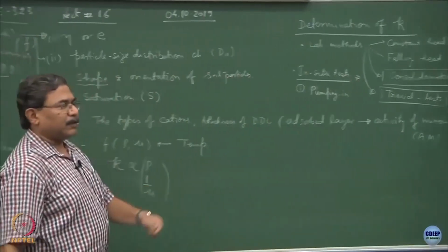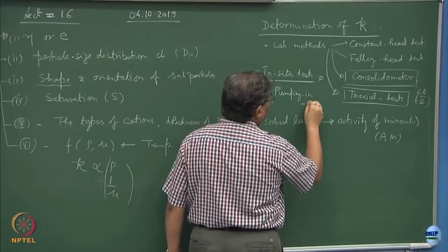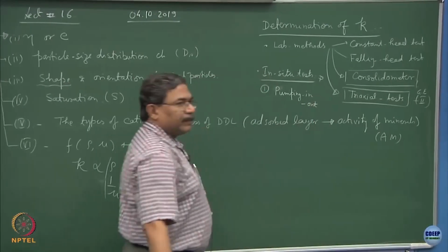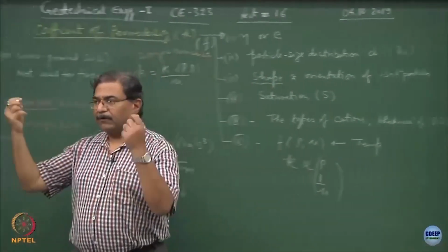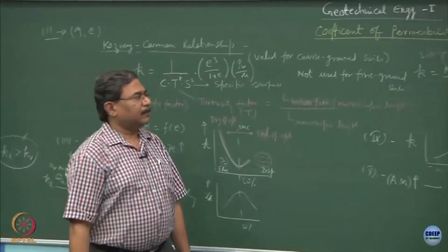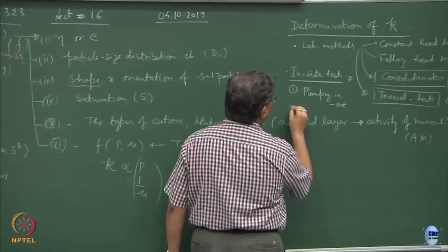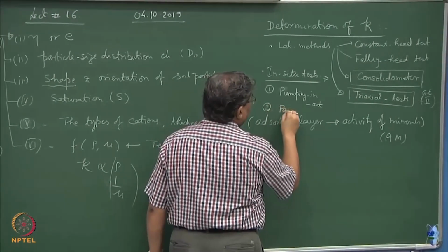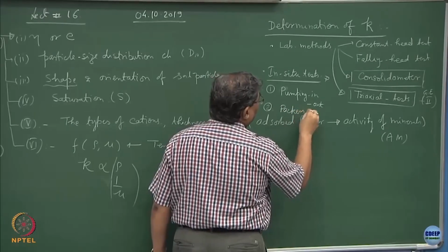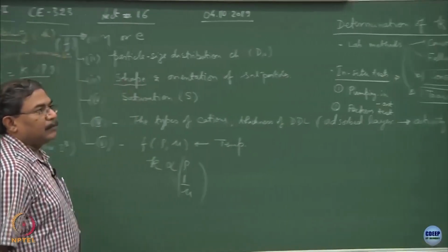So, we will discuss this, or it could be a pumping out test. What we do is, we drill a well and then pump out water or pump in water, and we see how much the drop in the head is going to take place in unit time. There is another series of tests which is known as the Packer's test.